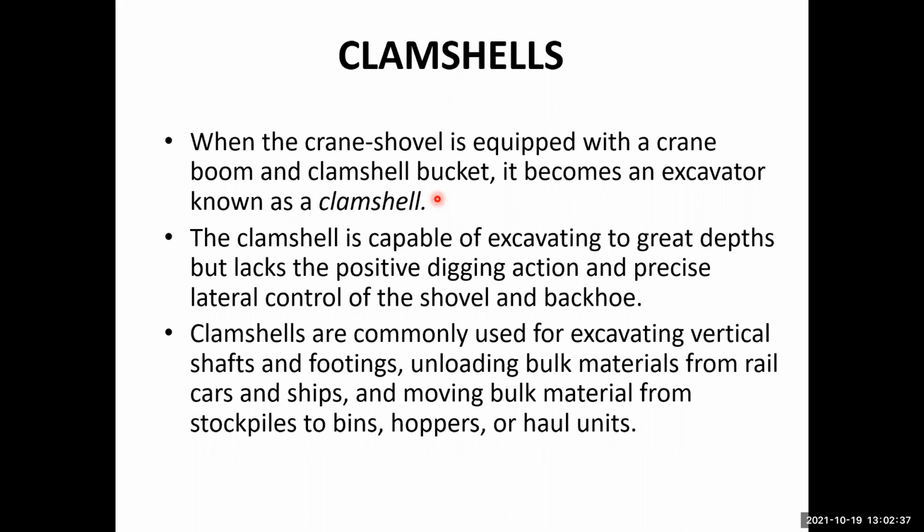On the crane we can put another type of bucket, which is known as the clamshell. The clamshell is capable of excavating to great depths, but lacks the positive digging action and precise lateral control of the shovel and bucket and the backhoe.